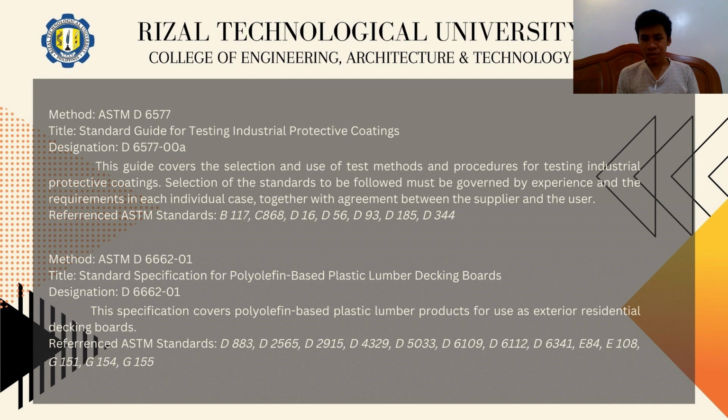Surface preparation or cleanliness prior to application of the coating can be critical to the proper performance of the coating. Results obtained in the tests cited in this guide may not be adequate for predicting coating service life of a specific coating system in specific environmental exposure. A suitable control coating system of known performance in the service environment should be included in the testing for comparison.